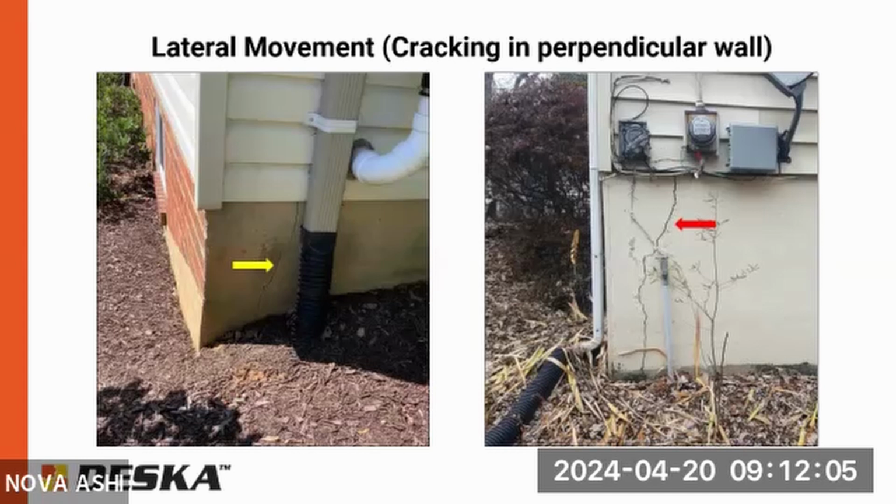So if you're ever at a house like this doing an inspection, what you really want to look at would be the front wall, the wall to the left here, as opposed to the wall with the actual crack in it. If it's finished and you can't see it, well, I would recommend removing the drywall typically, or having an engineer come out to look at it. We can only say what we can see.